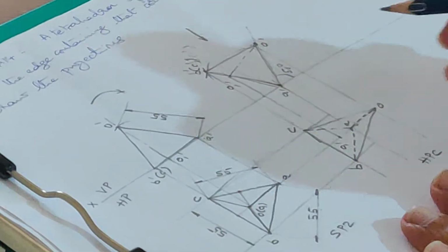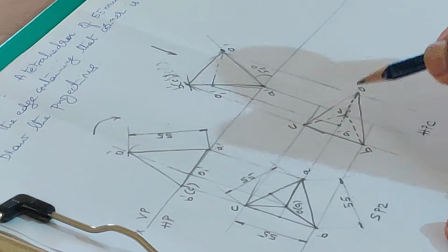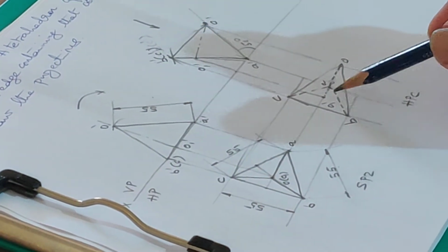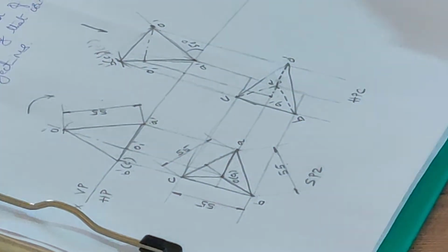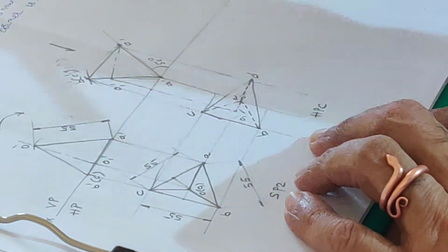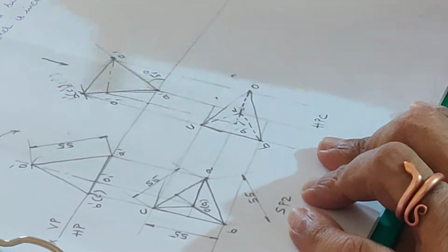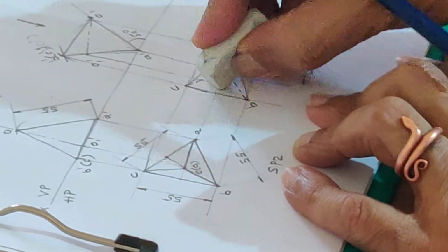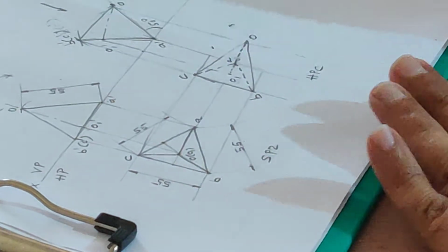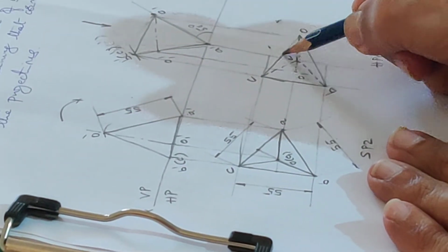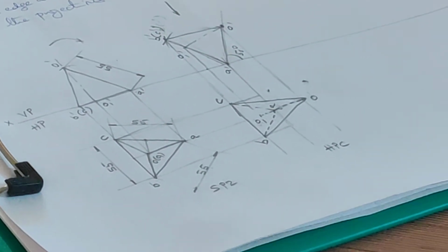Only A to O1 you will be able to show as a chain line because the remaining portion is overlapped by the dotted line. In fact, O1 is the top view of the axis. This is O dash. Sorry, there is no dash. So O and then O1. So this completes the top view in the second step, or in other words, we have satisfied the HP condition.